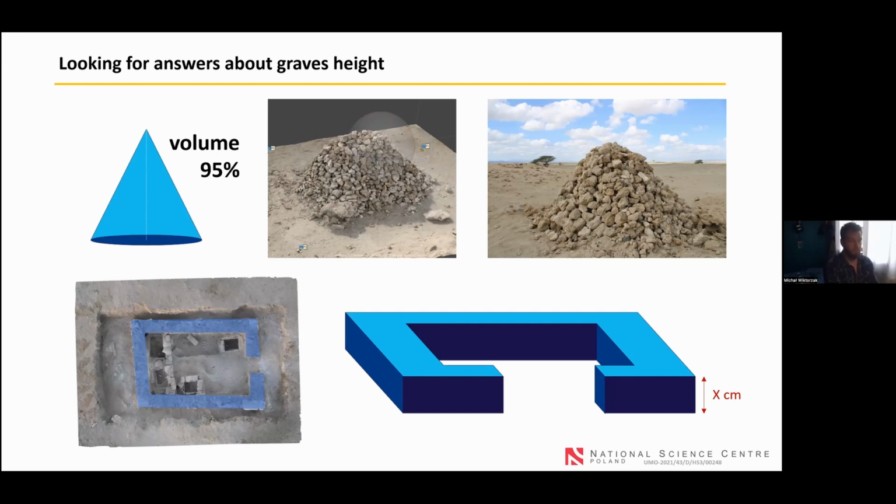We did it using photogrammetry by making a model of this rubble, then getting the volume using CloudCompare, and then thanks to orthophotos that have really good geolocation, we were able to get the area of this wall. So using really basic math, we can get the height of it by dividing the volume of this pile by the area of this wall.